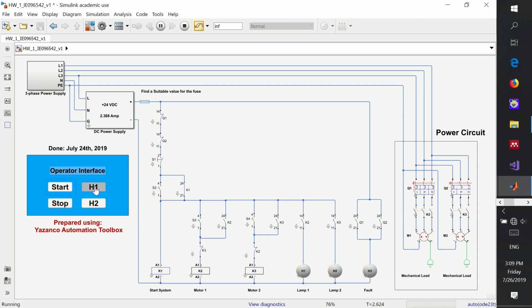Now we need to start the first motor, and remember that its preset value is actually limiting the current passing through it, since it needs about 100 amperes to start running. This is a huge induction motor, and you can see here now this contact is actually closed, telling that the first motor has overloaded, and the associated power contact is released. And here we have the open contact, so there is no current passing through this branch, and as a result we are unable to start the system anymore, as you can see here.